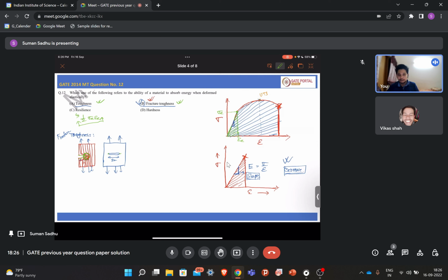So when stress concentration builds up, what will happen? Then this crack will start to propagate, right? So let's say this is your applied stress sigma. Here it will be something else, and here it will be some high value. That is given by the stress concentration factor Kt, that is sigma maximum, that means sigma near this tip, divided by sigma applied.